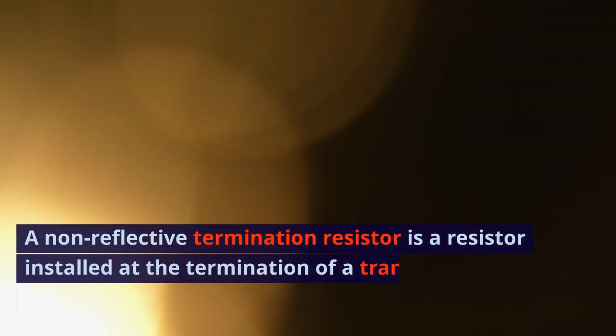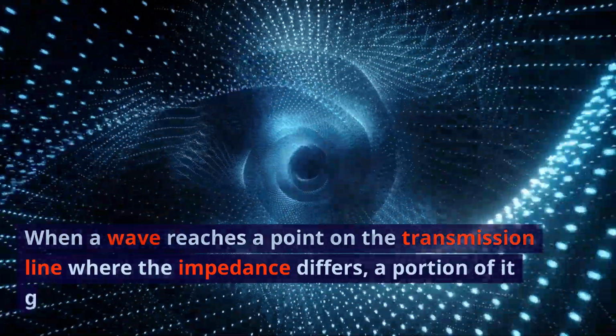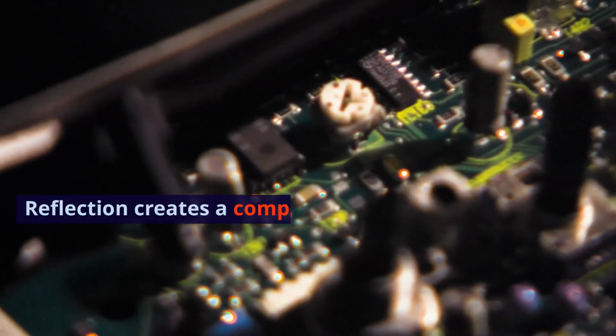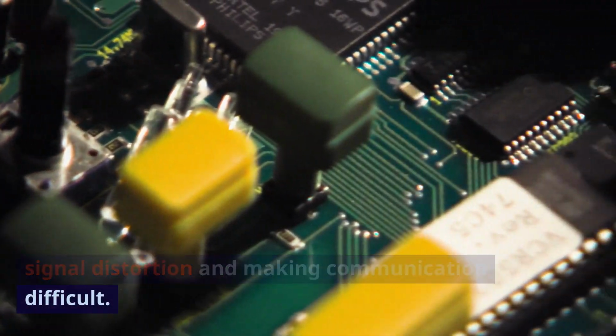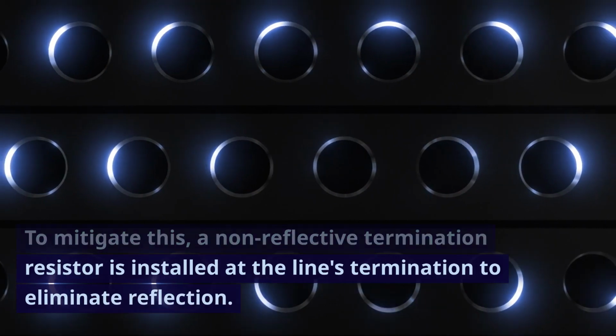A non-reflective termination resistor is a resistor installed at the termination of a transmission line to prevent wave reflection. When a wave reaches a point on the transmission line where the impedance differs, a portion of it gets reflected. Reflection creates a composite wave of forward-going and reflected waves, causing signal distortion and making communication difficult. To mitigate this, a non-reflective termination resistor is installed at the line's termination to eliminate reflection.